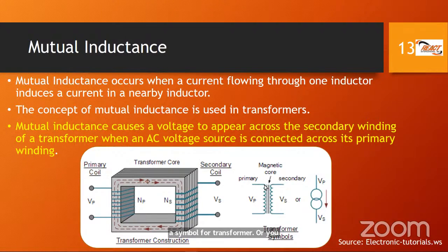And you'll notice, as we had mentioned before, this is an inductor symbol on the left-hand side, and this is an inductor symbol on the right-hand side. And then we have an iron core that's represented by these two parallel lines. So together, these two inductors put together with the iron core form a transformer. You'll see how we reuse the inductor symbol in creating the symbol for a transformer, because that's exactly what it is: two coils of wire, or inductors, that are employed together.